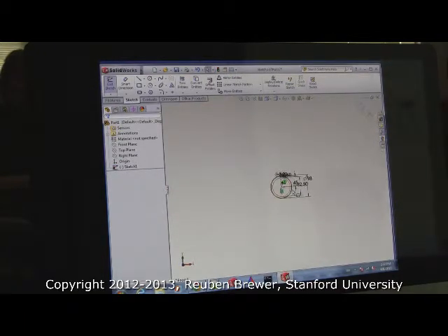Okay, now zoom way out. And we're going to do the same thing. So Smart Dimension, and try to click. And you will notice you can't. You see how it's highlighting weird stuff? For me, it keeps highlighting the 45 instead of the line. And now it's highlighting these weird things.